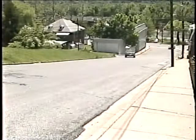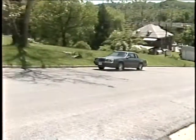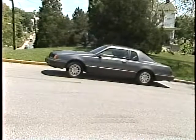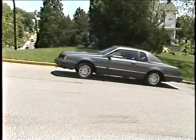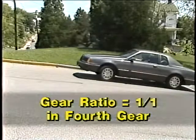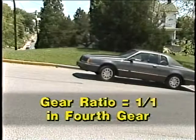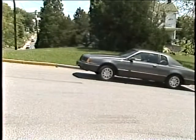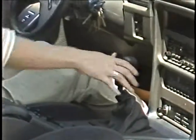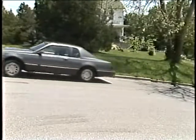Or what if you had to stop at a stop sign while on a steep hill? Well, if you try to start up in fourth gear, you may spend the rest of the day at the stop sign. That's because the gear ratio in fourth gear is about 1 to 1. Your potential for reaching a high speed will be there, but there's not enough torque to get you going. Another gear arrangement would be more suitable in this situation. In first gear, you have enough torque to get going again.